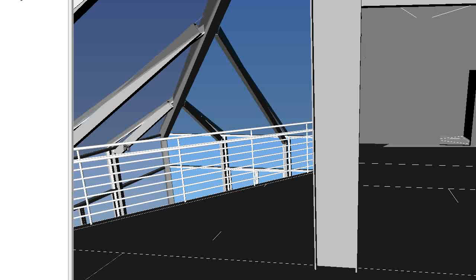And lastly, we're going to talk about viewpoints. Viewpoints are a snapshot of the model as it's displayed in the scene. The model can be navigated to a required view. Items of the model can be hidden, and other items can be rendered with different materials and lighting. Then the finished scene can be saved as a viewpoint for further reference. In addition, you can add a variety of comments and redline tags to a saved viewpoint or combine viewpoints with a quick animation.